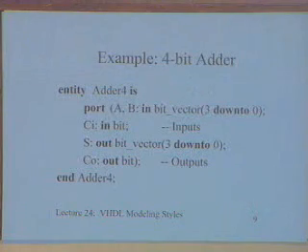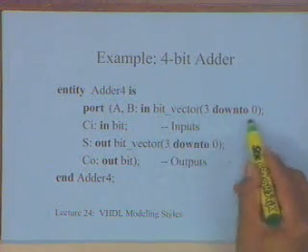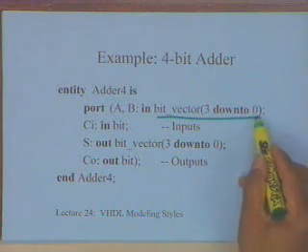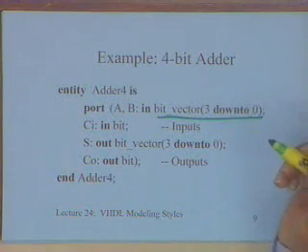So now let's use that 1-bit adder and try to build a 4-bit adder. I have this entity adder4, and you can see the structured data type. You are saying bit vector 3 down to 0. Bit vector is the name of this.